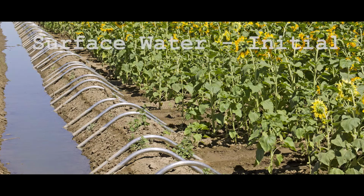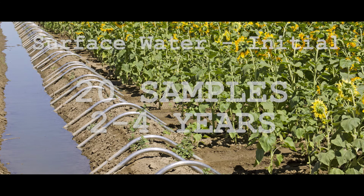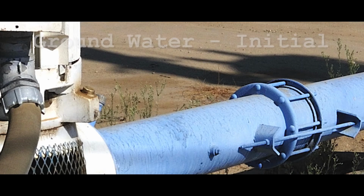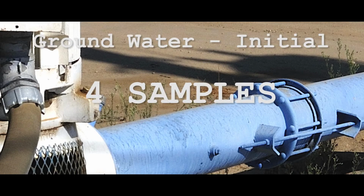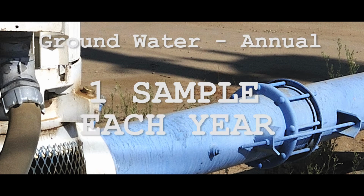Number of water samples required. For surface water, an initial 20 samples need to be collected over 2 to 4 years. After that, 5 samples need to be collected each year. For groundwater, an initial 4 samples need to be collected over 1 year. After that, 1 sample needs to be collected each year.